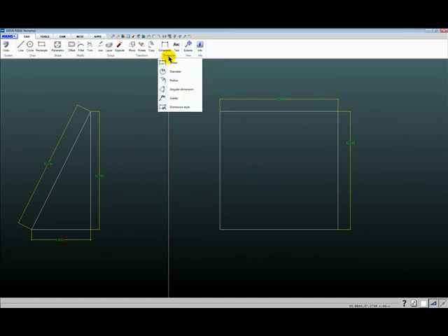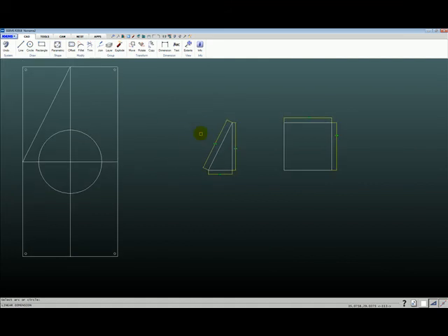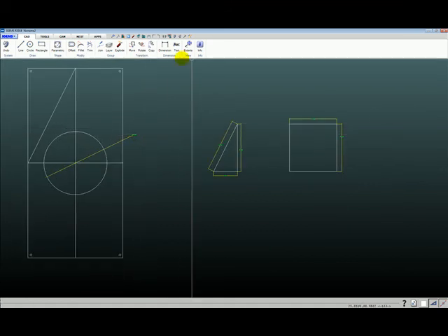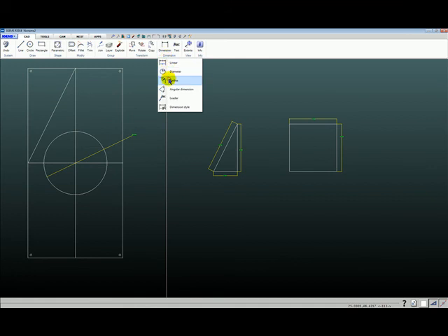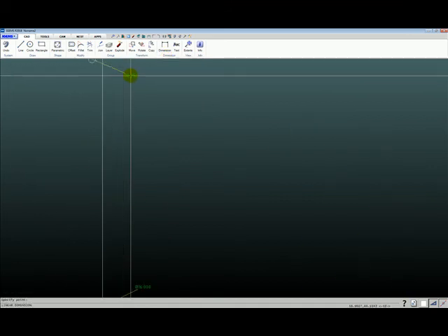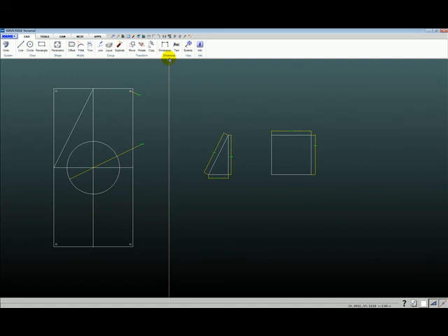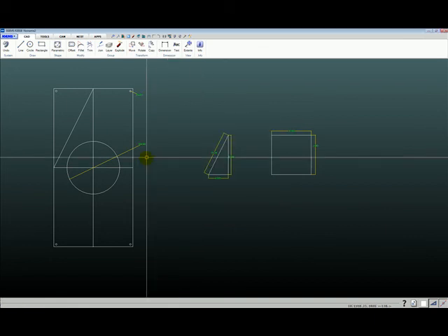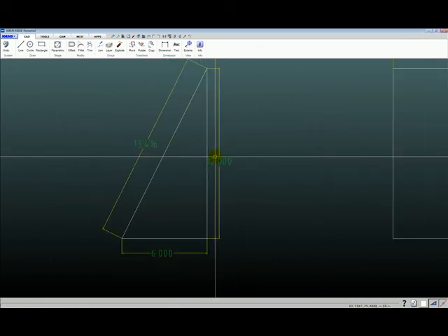Also, underneath the dimensions submenu, you've got other options if you want to do a diameter, so you can dimension a circle, or you can do a radius if you prefer to know what the radius is. Angles, too. If you click on the dimension style, then you can define things like how large you want that text to be, so if you want to make that text a little bit bigger, and how many places after the decimal you want displayed, and that'll update once you change that.